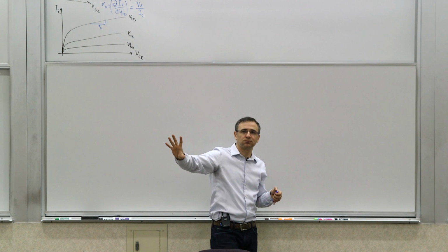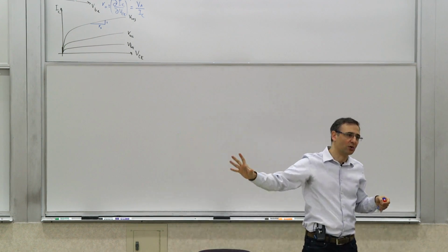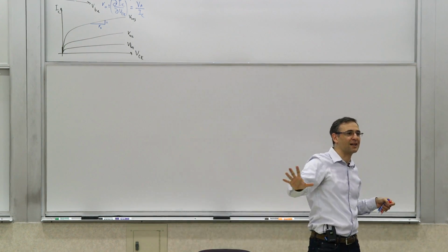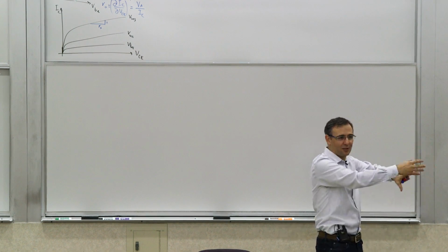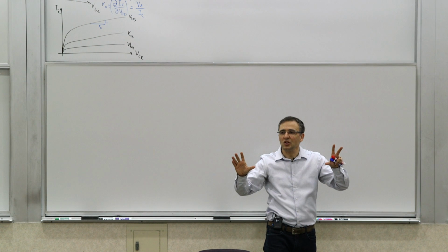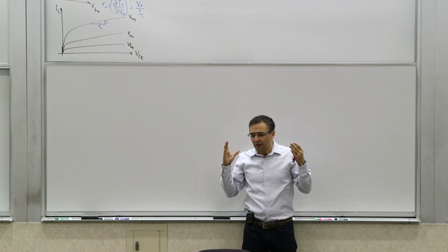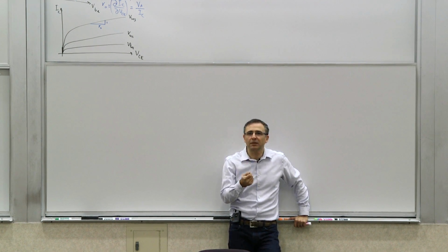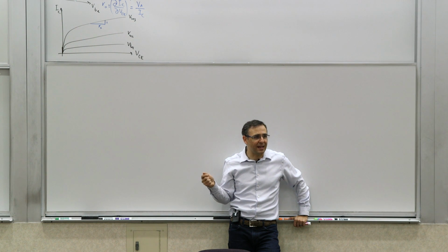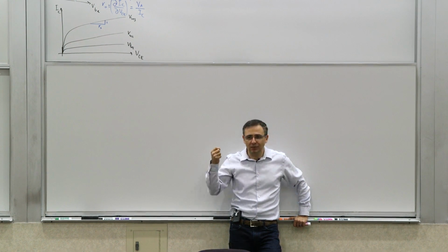Some regions of this continuum we call voltage amplifiers, somewhat arbitrarily, and some regions are called current amplifiers, again arbitrarily, right? So here's the thing to think about. We have this device, and we want to make a voltage amp, meaning we want to create an output that's a voltage, an amplified version of the fluctuations at the input. We have a device that converts the voltage fluctuations to current.